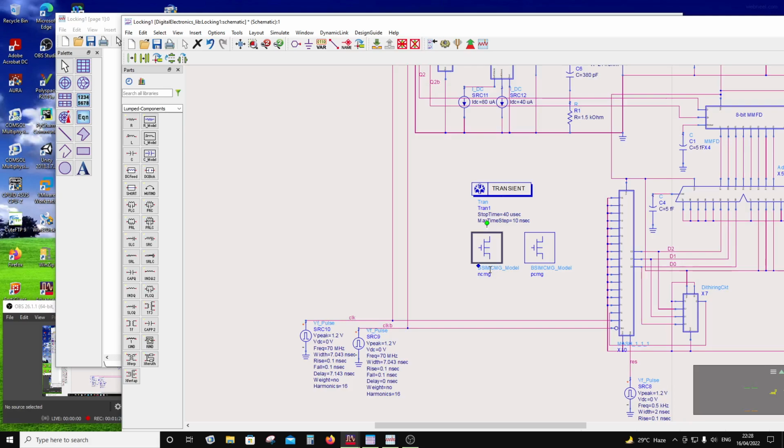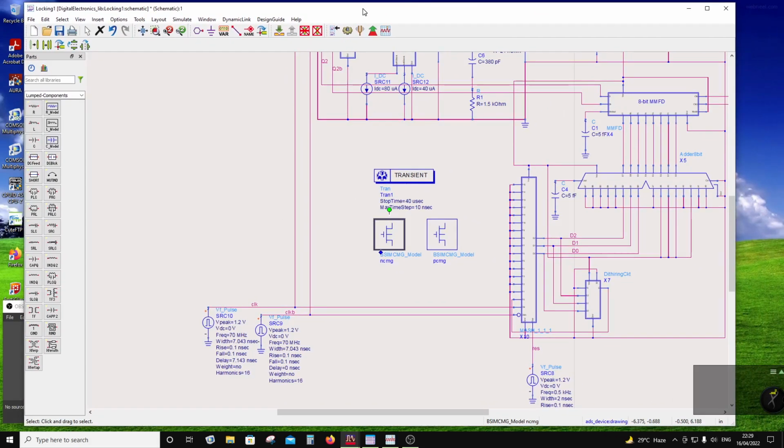So this is a CMG tri-gate model. I did the simulations, then extracted the parameters, and based on that I did the modeling of 7 nanometer MOSFETs or FinFETs. The fin width is 5 nanometer. I have earlier also shown on my LinkedIn account what I did. So what I have here is a 7 nanometer process, PMOS and NMOS.